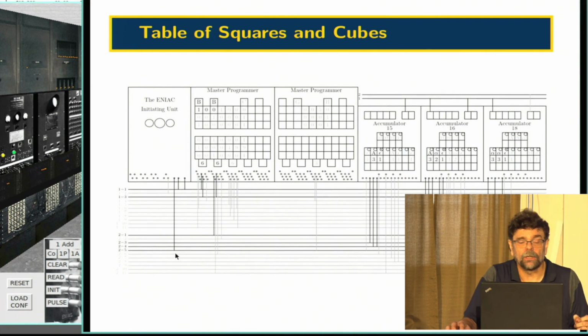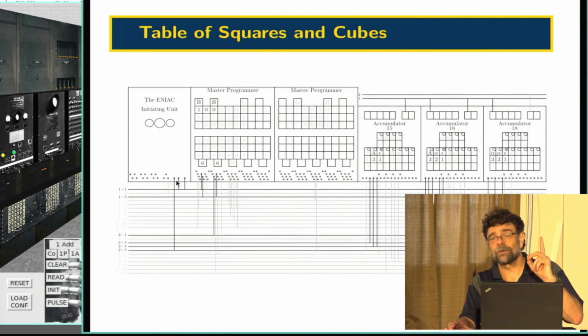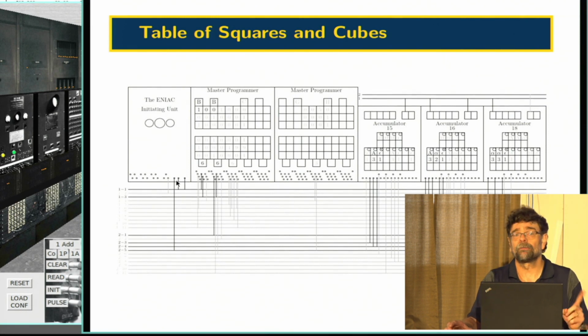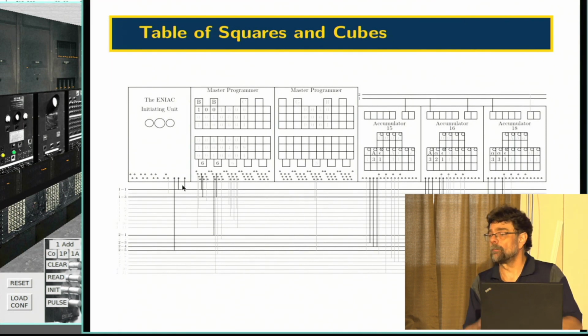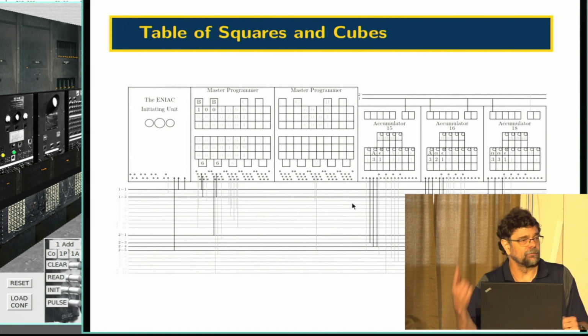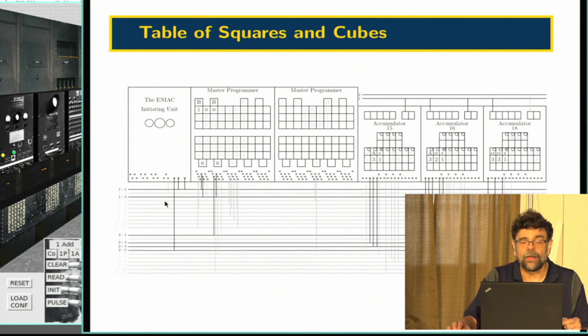When we do the punching, that happens down here with the signal 2, 5. That sends a signal up into here that initiates the punch operation. But because the card punch takes 0.6 of a second per card, we might have to wait on it. And so this signal right beside it is the output that says, the punch is now ready for some more information. And we use that to trigger the next iteration of the loop. So that's what's happening over here kind of in the control side of it.